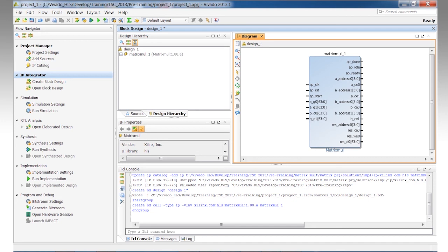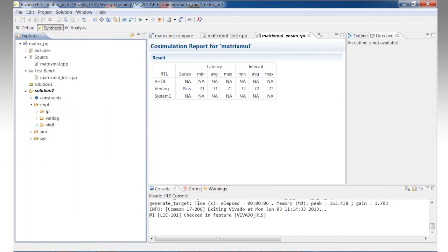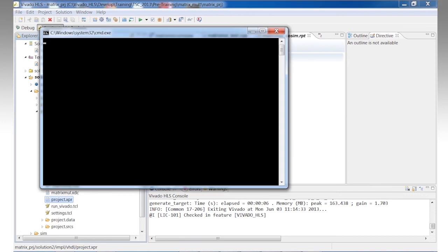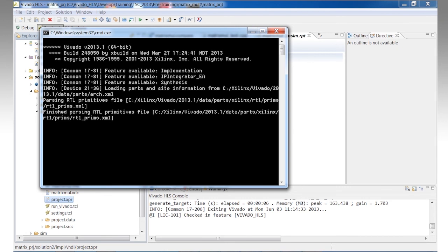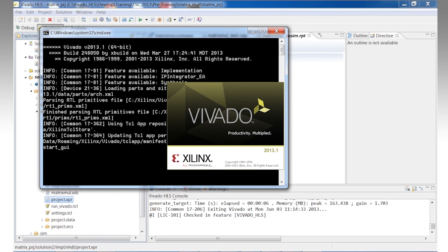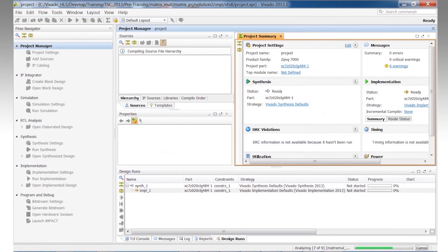If we go back to Vivado HLS, alternatively, if we go into the Verilog or VHDL directories, let's just choose VHDL. We could click on the Vivado project, and it will take this design, instantiate it in a Vivado project for us with the RTL test bench that we just generated using RTL Sim, and provide that for analysis. And here we have our design inside a Vivado project where we can start to do detailed analysis if we prefer working at the RT level on this.